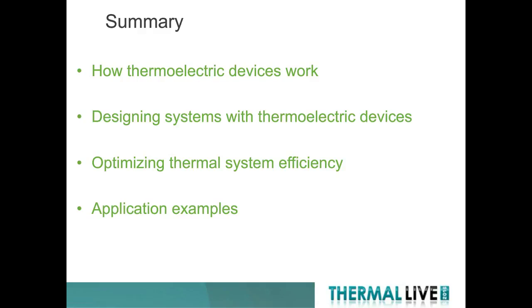Okay. The next question is from Mike from Viasat. Can TECs be used in an environment where there's high vibration and large temperature swings, like over 100 degrees Celsius? Well, the easy answer is yes, but as Abhishek mentioned earlier in his comment on the reliability of these thermoelectric devices, a lot of it comes down to understanding those applications ahead of time and then building up the infrastructure either within the device or around the device to make sure they're reliable.